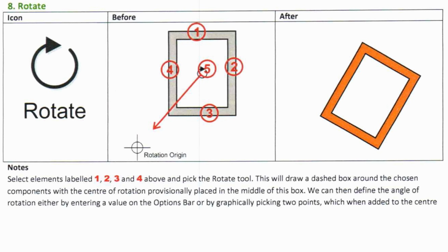Best practices: use reference points or guides for precise rotation. Combine with snaps to maintain alignment. Avoid rotating hosted elements unless repositioning is intentional.